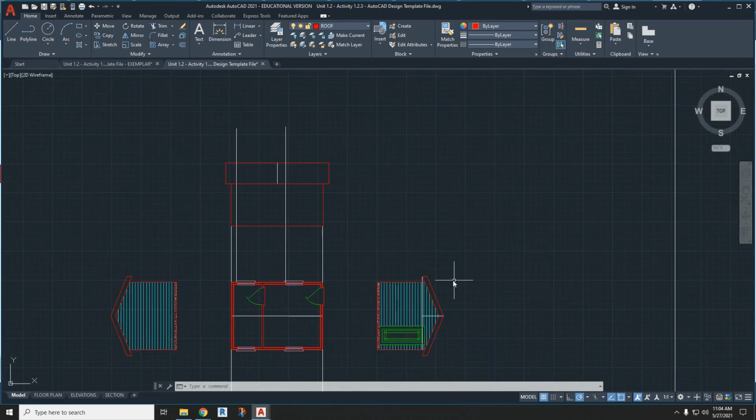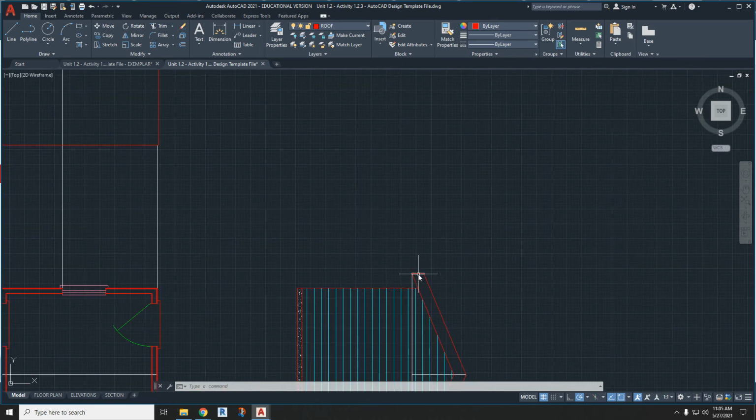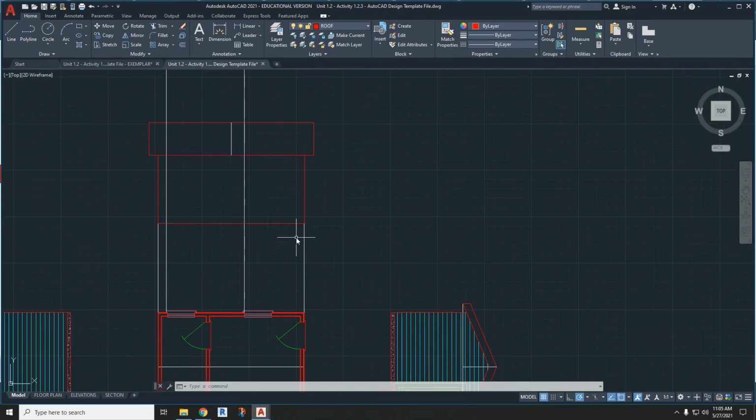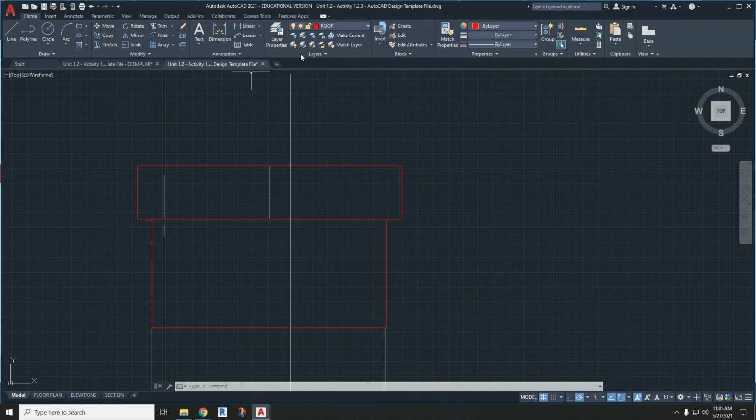And again, when you're looking from the side, you see the fascia board, which is the thickness. Again, this is not a fully detailed thing. The fascia board, we'll assume it's just going to be a 1 by 10. Normally, it would actually be a little bit larger. It might be a 1 by 12, but we're just going to make it work for now. So a line, go up 9.25 inches, and then cut across. Delete this little piece here. That's my fascia board. This is the shingles I'll see.